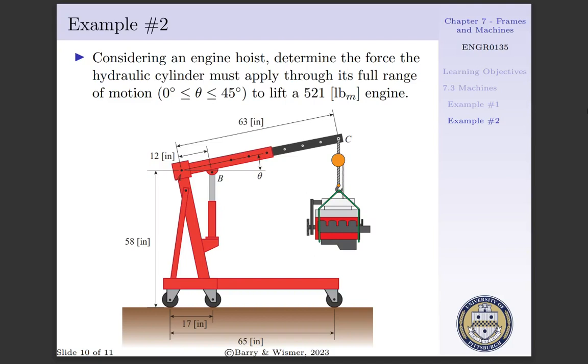In our diagram below, pin A will be the point of rotation that the arm of the engine hoist will rotate about. As we put a force at point B, as exerted by the hydraulic cylinder, the arm will lift. Our engine weight applied at point C will always act downward, and the force exerted by the hydraulic cylinder at point B will always act upward.